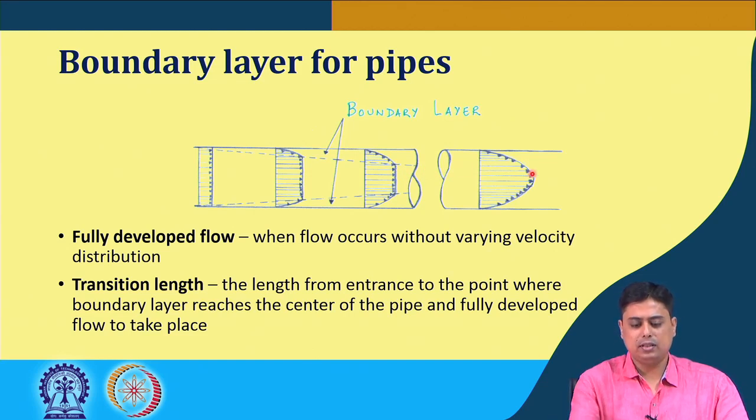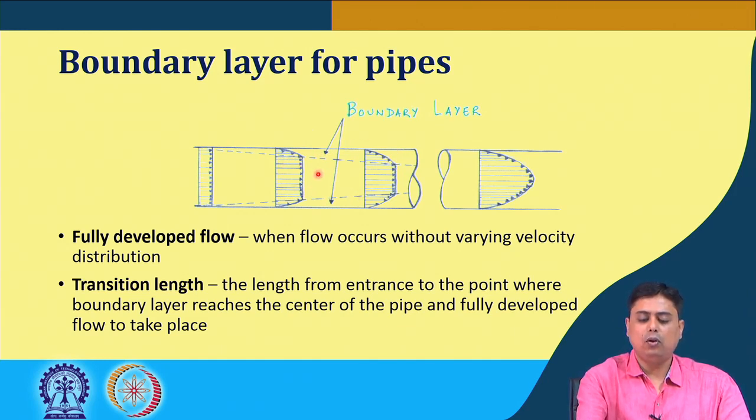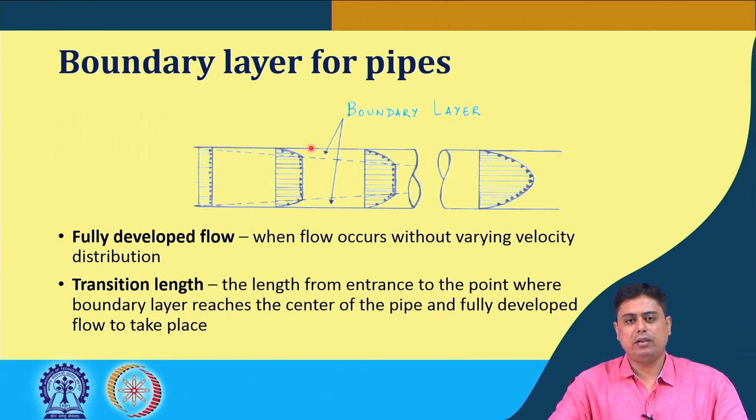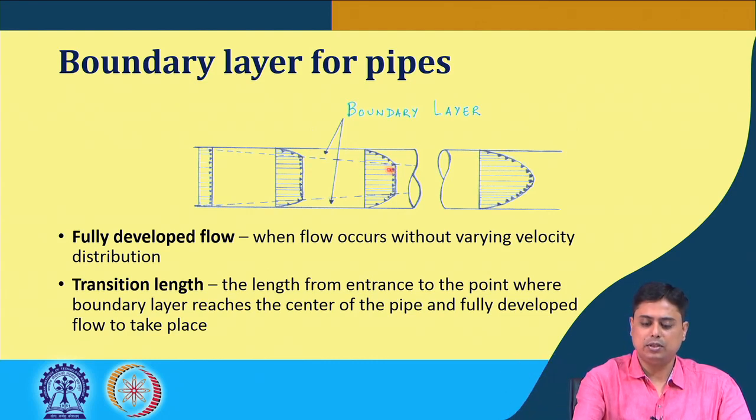So, what happens is that as soon as it enters, the boundary layer starts to develop, okay, and in the developing region, the fluid flows in a rod-like manner, because here the fluid movement is there and here the boundary layer. So, here the flow is very low, as you can see. We can understand that in the boundary layer we have seen there is a laminar flow or the viscous sublayer, buffer layer, and then the turbulent flow or the free stream region comes into play.